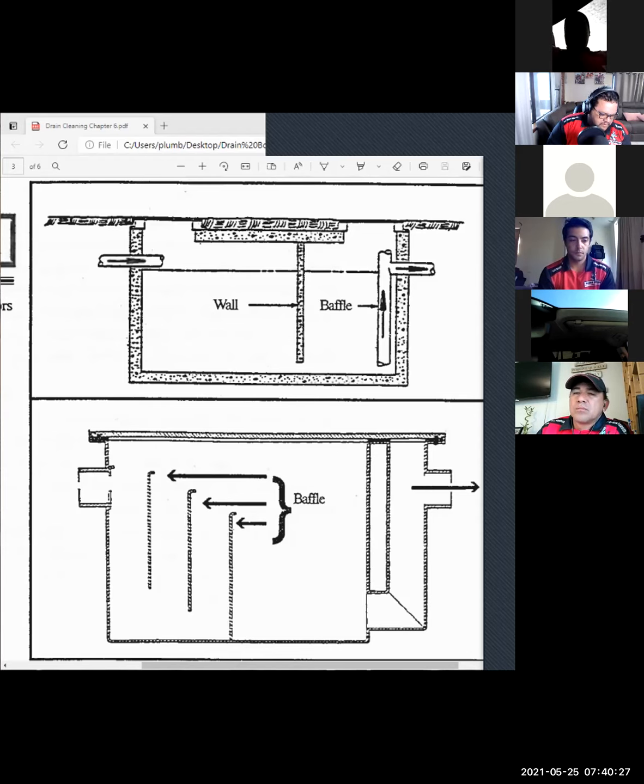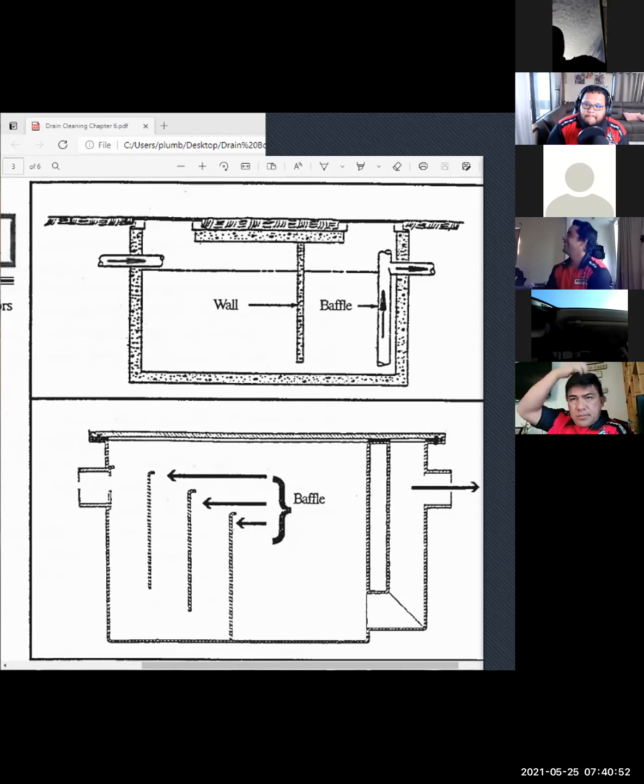Josh, let me interrupt there. That's actually not correct, and I'll tell you why. In the old days, you didn't have to have anything to the grease trap except for the triple compartment sink where you're washing the dishes. That's why you went into these old places and they only had that small thing under the sink. Then when they went into this grease management program, they started doing the sizing off that Appendix H, and kitchens and meals, lunches, breakfasts, and dinners. That's when large capacity grease traps went in.